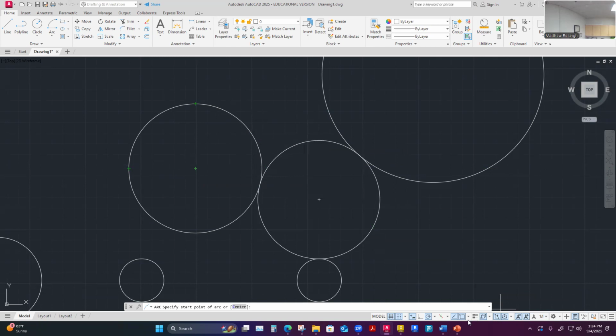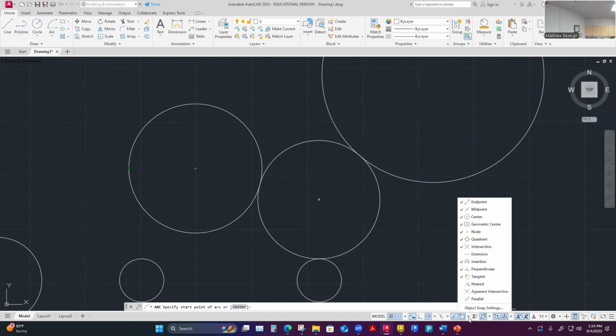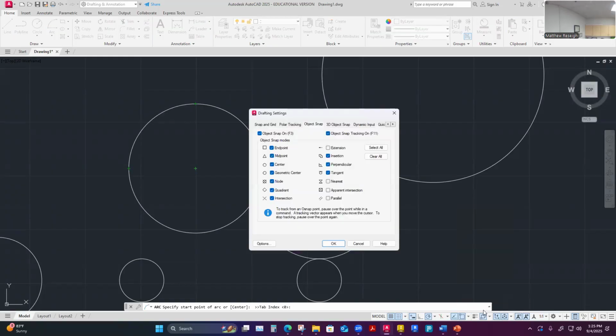How you verify what those are is down here in your O snaps list. It's these, and they kind of give a little picture. But I think if I look at my object snap settings down at the bottom, it's like another menu within a menu. This one I like because it at least shows the symbols that are going to show up in relation to what object snaps are available on that geometry.